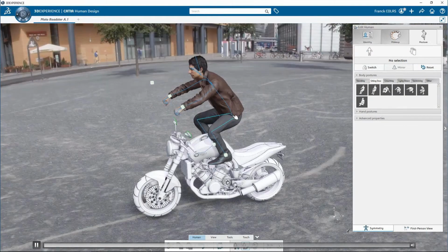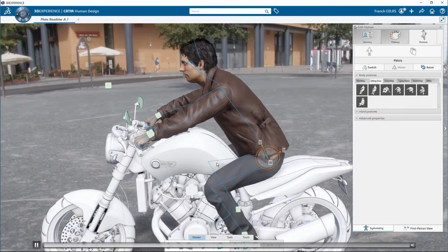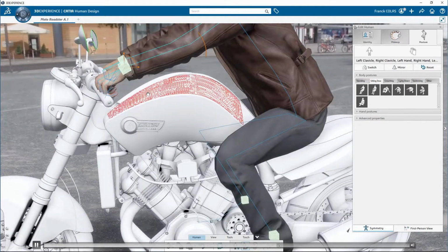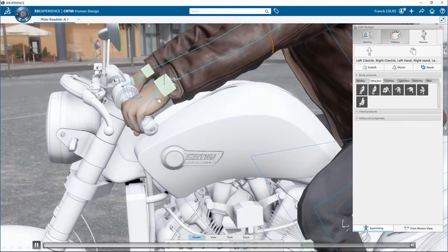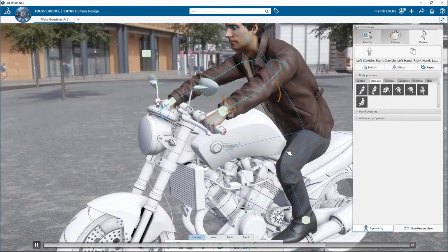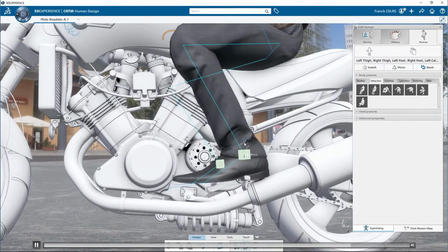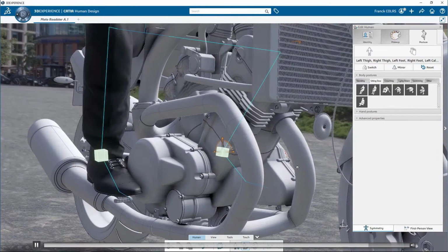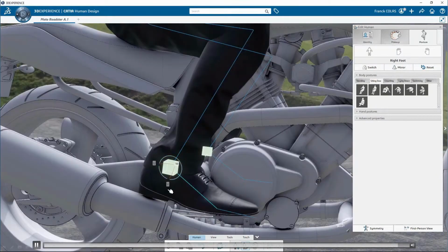And so we're going to put this human in a driving position. And then at that point, we can independently position the hands. And there's even a feature to auto grab objects like those hand grips, and collision detection, things like that. Human design mannequins have built-in inverse kinematics. So by default, you cannot overextend the joint rotation unless you override it. There is a setting there.